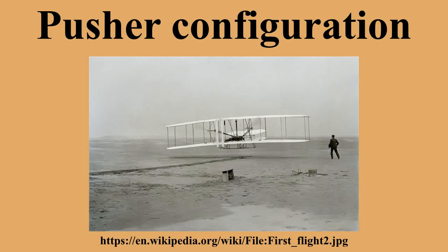Assuming the engine cannot be run in the reverse direction, the handedness of the propeller must be reversed. The loads on the thrust race are also reversed, because the pusher propeller is pushing into the engine rather than pulling away from it as in a tractor. Some modern engines designed for light aircraft are fitted with a thrust race suitable for both pushing and pulling, but others require a different part depending on which sense they are operating.